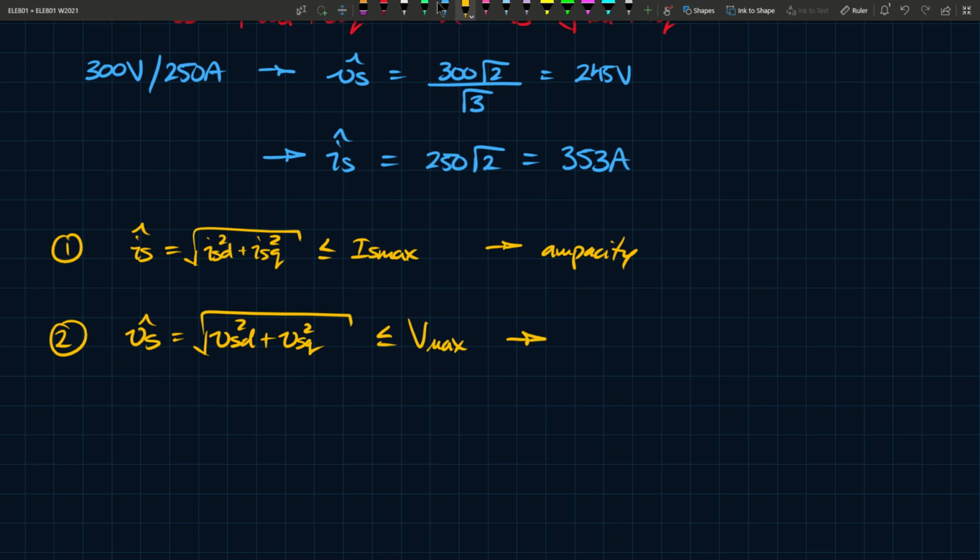And this limit depends directly on the inverter. We've only talked about these machines from the perspective of control, modeling, and theoretical things like equations, but you have to understand that the voltages we're applying to these machines are usually being generated by power electronic devices. Those devices have limits on how they can operate, their total voltage, current, power, all these things. So you can imagine that this limit is essentially an inverter voltage ceiling. Let's say inverter voltage.